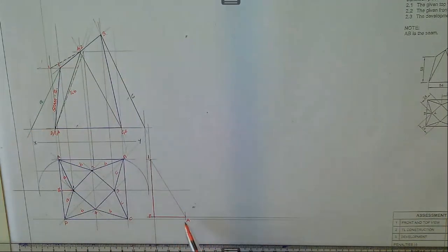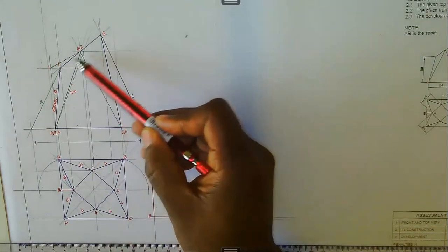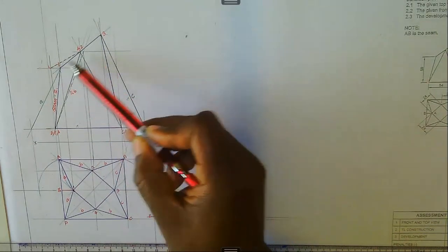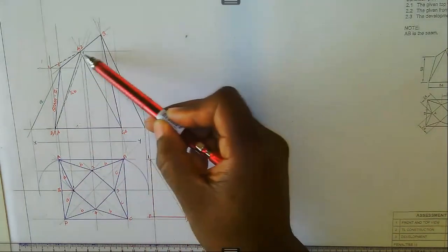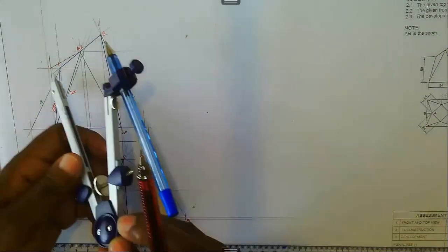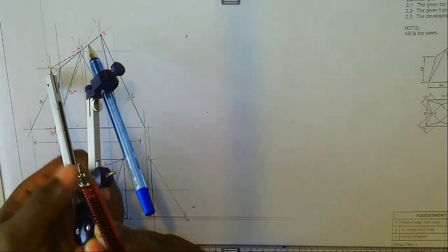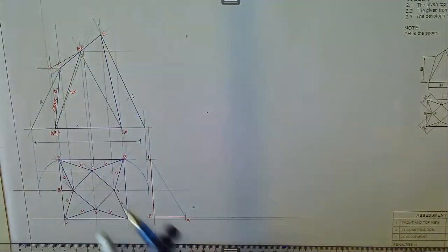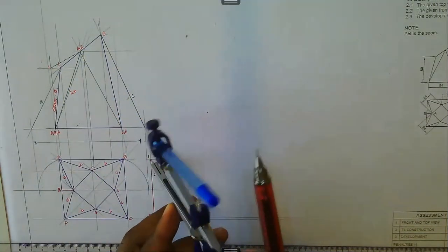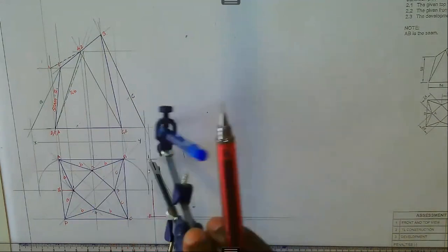Now, once you have gotten point A, like this, the next point that we want to find is point 2. Remember, we are not going to take from here, neither are we going to take from there, because we need the true length. We stood at point 2, rabatted like that, took this one up and connected with that. So we are going to take this. You take that as a true length, then you describe an arc like this.